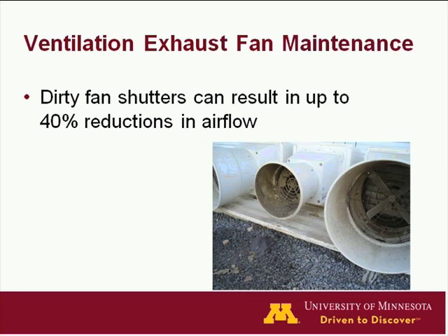Dirty fan shutters can certainly reduce airflow rate and reduce efficiency, as much as a 40% reduction in the airflow rate. That was some work that was done here in Minnesota quite a few years ago. And it's just as simple as making sure the shutters are operating right and lubricated properly.